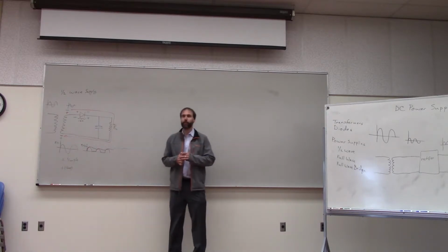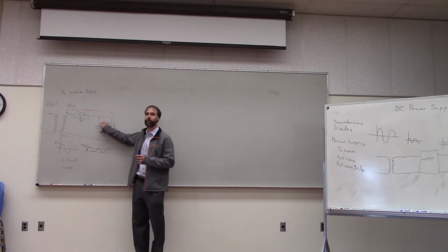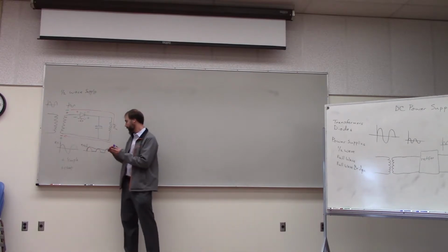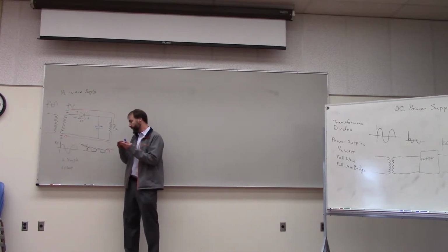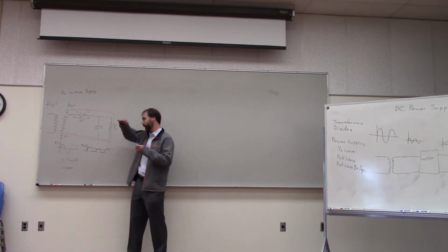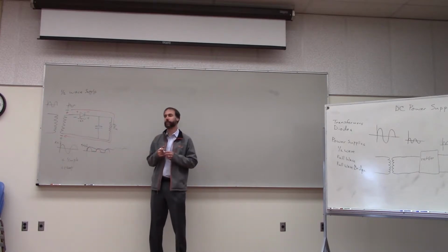If you added more capacitors, would it make it smoother? Well, if you had a bigger capacitor, it would be smoother. Exactly right, because it would not discharge as much voltage during the interim, so it would go down less. With the capacitors, do you have to match your capacitor to your frequency?